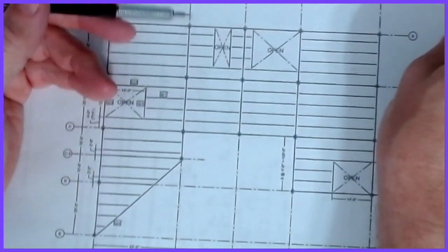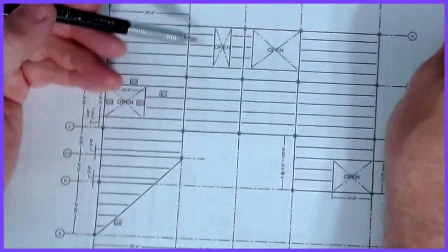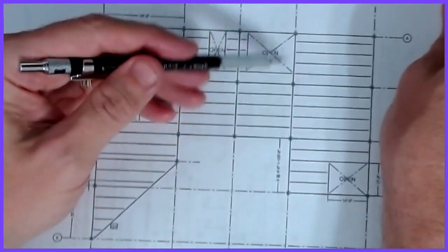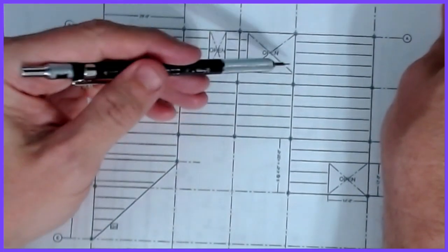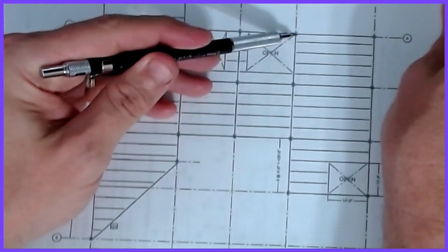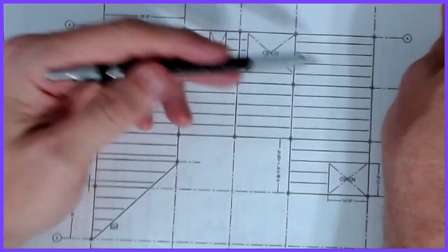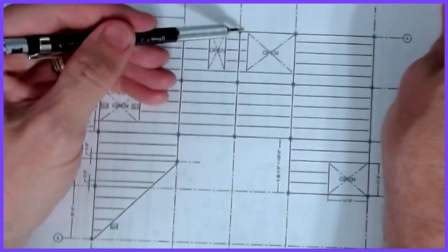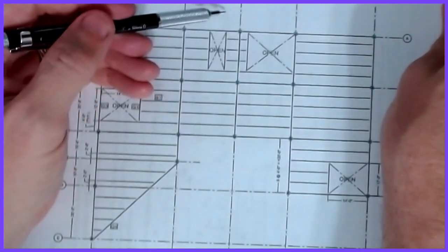It's not necessarily that difficult, but anytime you have a structure with an opening, you've got to be a little bit more exact. I mean, look at this bay. Most of the load is gone because the opening is here, right? So this column gets next to no load on it. It does get a little bit from the other side over here, but from this bay there won't be a whole lot of load going into it. And this one just gets a little sliver, whatever that dimension ends up being.